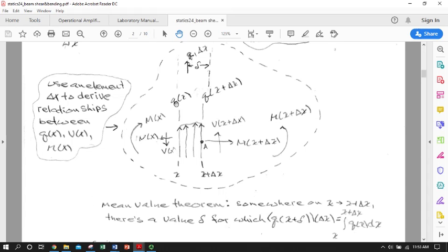So if we had a function q for that distributed load, that wouldn't be too hard. All we'd have to do is integrate q between x and x plus delta x, and we'd have an effective resultant force. We wouldn't quite know where to apply it, but if we're only taking the forces in the y, it doesn't really matter. Where it matters is when we start taking moments.